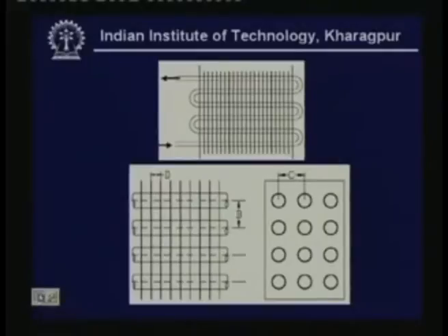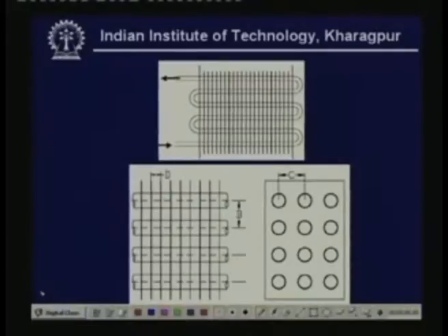As you know, we have discussed this in the last class. I have shown you the typical fin and tube type of condenser, and this is the face area. We have to find out what the face area is, and we have also defined certain parameters. For example, B is the center to center distance between two consecutive tubes in a row. This value is given.